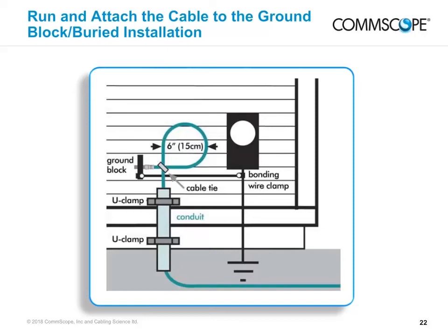As a last resort, you may drive an 8-foot ground rod into the earth and attach the bonding wire to that, but you will need to ground all of the grounds of the residence to that rod. Bond mobile homes at the electrical service tap. If there is no service tap, you may bond to the frame of the mobile home using a wire no smaller than 12 AWG. Never bond to the siding of a mobile home.